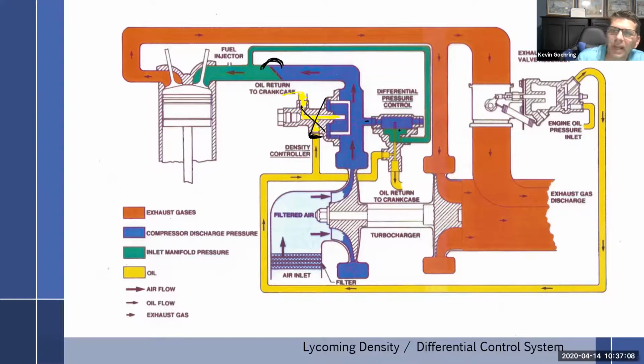So as soon as this gets to more than 2 PSI, it just opens up. It dumps all the oil out. This guy over here is saying, I want more pressure, but this one says, I don't care. I'm going to open up and just dump out all the oil. So it doesn't matter what you want because I just gave it a way through. And so all the oil from here starts draining off. Well, it doesn't necessarily drain off. It drains off to a point where this